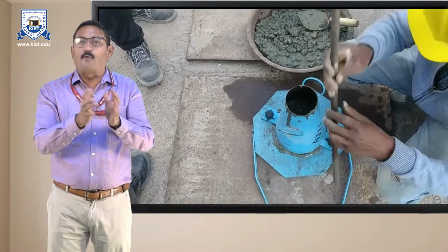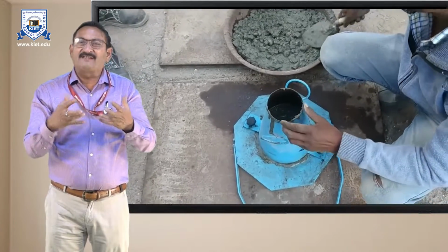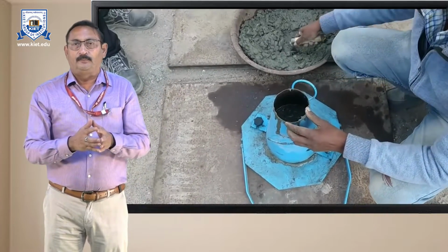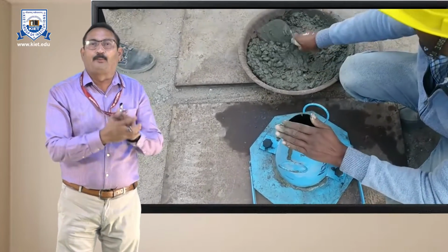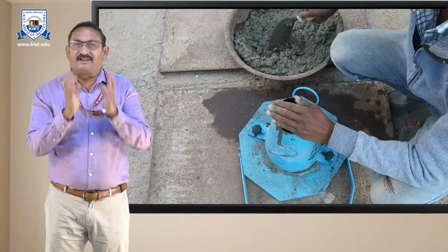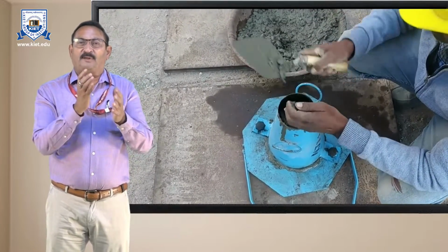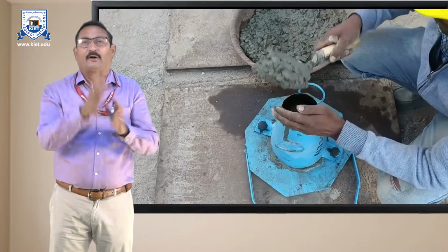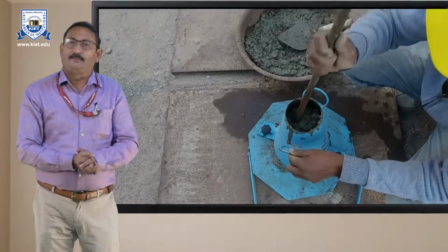Actually, the aim of quality control is to limit the variability as much as practicable. The statistical quality control method provides a scientific approach to the concrete designer to understand the realistic variability of the material, so as to lay down a specification with proper tolerance to cater for unavoidable variations.